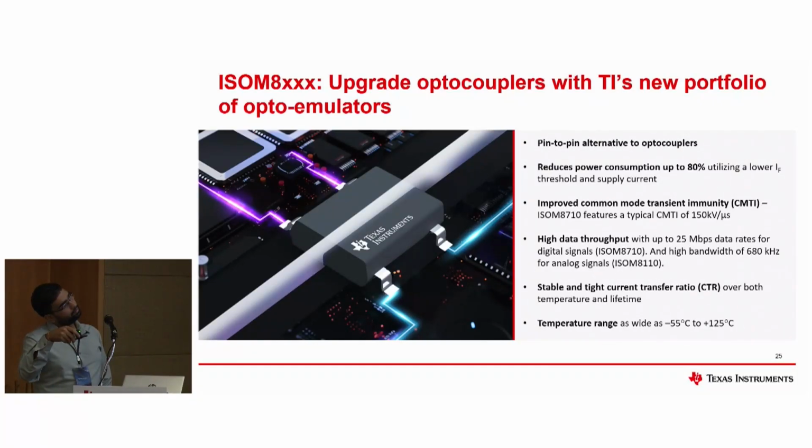It has 25 Mbps of operational speed for a single channel opto. The CTR, as I said, we have a very flat CTR response across the operating current. Generally, if you see optocouplers, the CTR variation throughout IF changes vigorously, more than 100% variation, whereas we have it under control, tri-temp, between 100 to 150%. When I say 150%, I mean if your input forward current is X and Y is your drawn output current, then Y by X, IC by IF, is CTR.